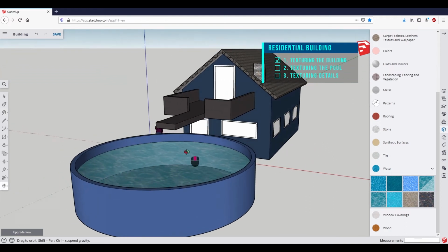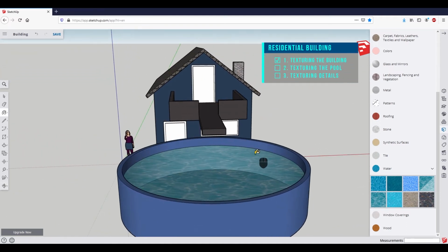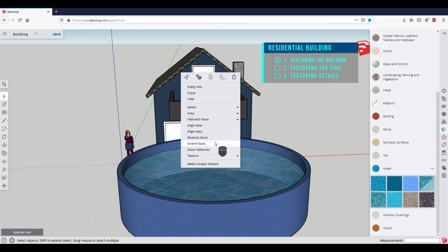You will notice that the faces below the water surface are not filled yet. And because we can't fill through faces, we have to hide the overlaying face first. So pick the select tool and now right-click on the water surface. In the submenu, click on Hide.